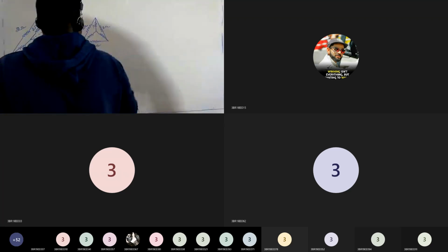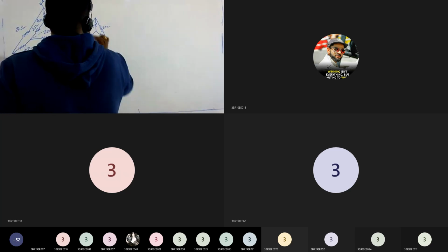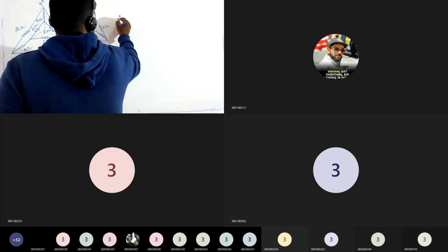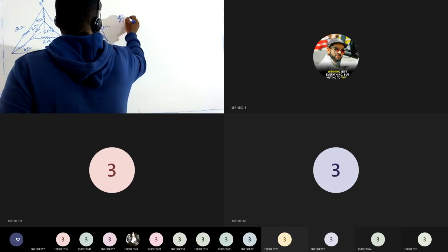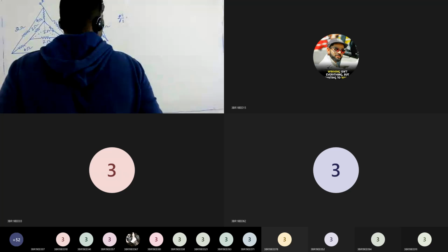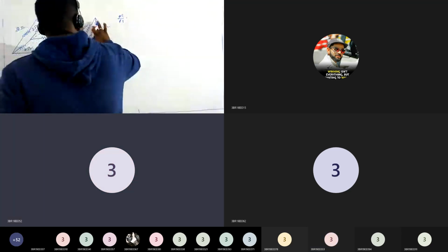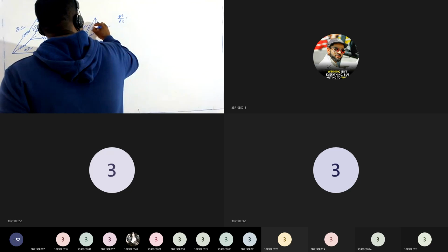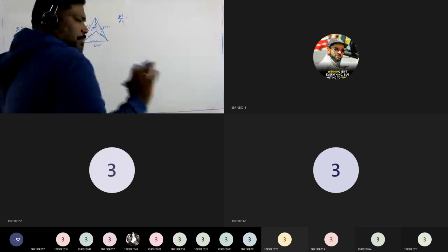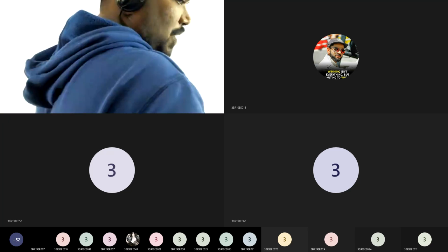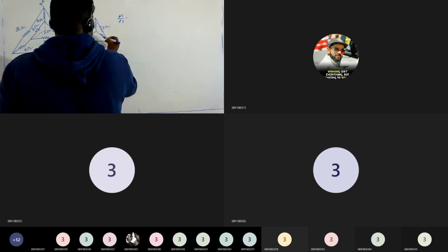To calculate this value, delta to star: 2 into 2 divided by the sum of all, 4 divided by 6. It is 2 by 3, the value is 0.66 ohms. Since all the resistance values are the same in the delta connected network, I get the same values for all branches.